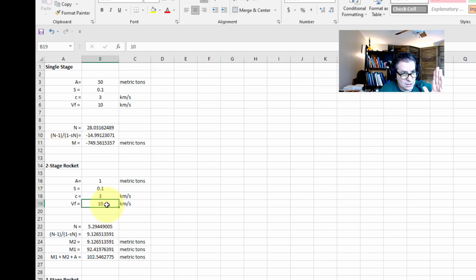And not only going vertically, you're also going through the atmosphere, and that burns a lot of fuel just to fight that air resistance. So there are drag losses and gravity losses at the initial part of the launch as it's trying to reach altitude to get into orbit. So that's why that's increased to 10 as a typical example.